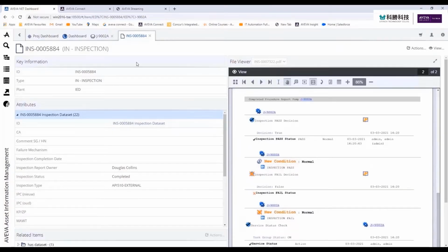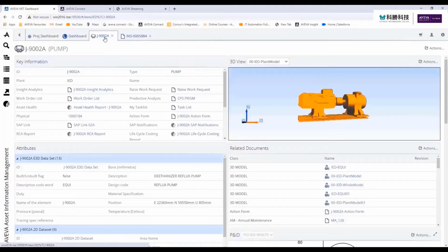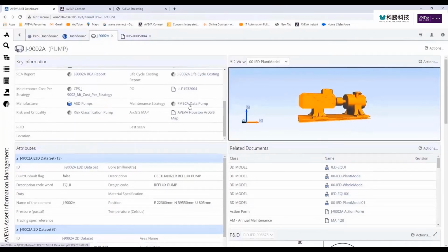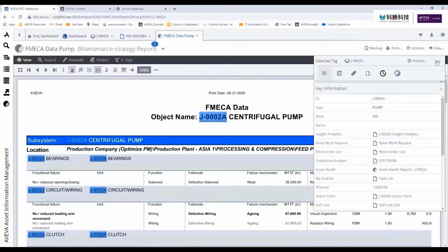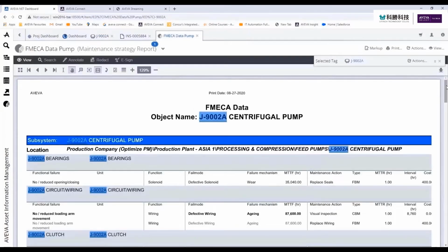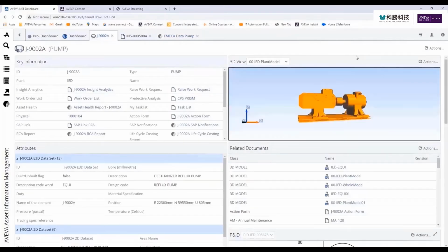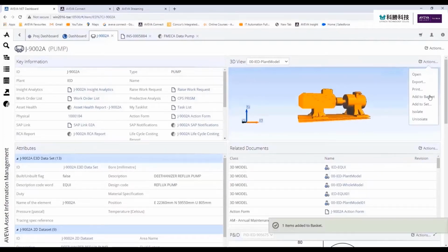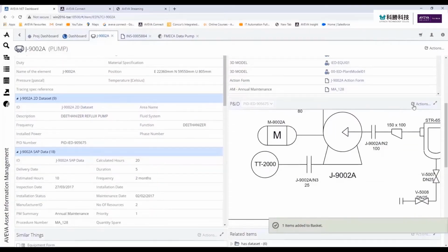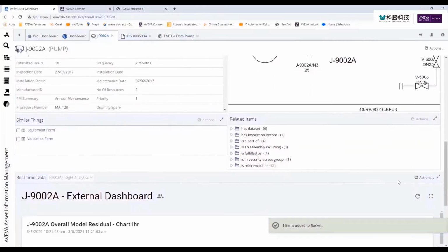The analyst can access a range of other documents, in this case asset reliability documents, reviewing the failure mode and the effect criticality reports to have a clear understanding of the overall asset reliability before taking any action. After this first analysis, the Monitoring and Diagnostic Center decides to plan an inspection to further investigate if this is a sensor calibration issue or is a mechanical problem.